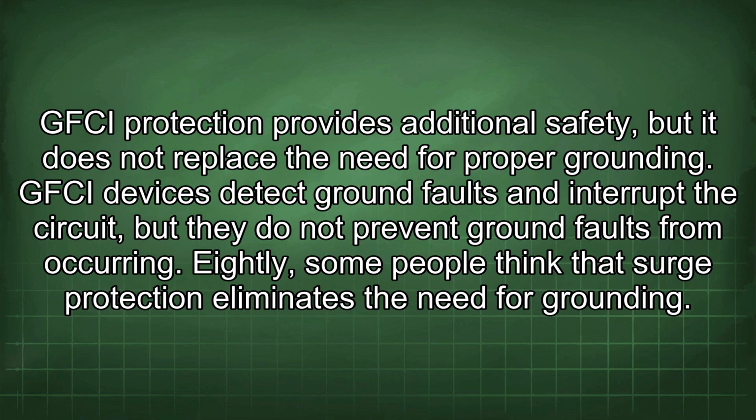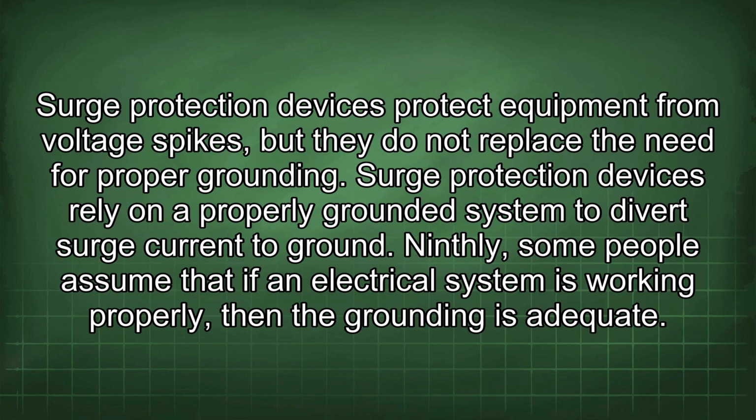Eighthly, some people think that surge protection eliminates the need for grounding. Surge protection devices protect equipment from voltage spikes, but they do not replace the need for proper grounding. Surge protection devices rely on a properly grounded system to divert surge current to ground.